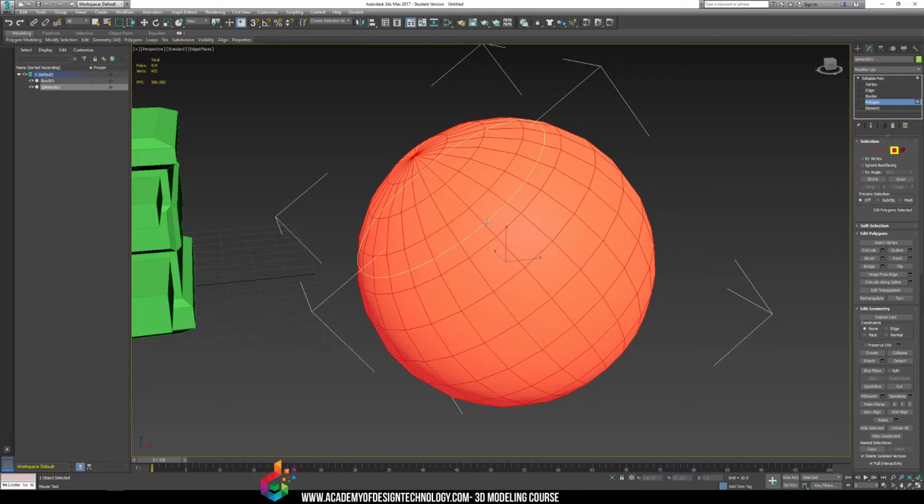What Swift Loop does is it tries to create a loop according to your 3D model's path. According to the other paths in your 3D model, this one will try and create a loop as best as possible. You can drag your mouse over your model. You don't even have to left click or right click. Just drag your mouse over the model with edit loop on, and you can see it's already going to preview where, if you left click, it will create new segments for you to play around with.